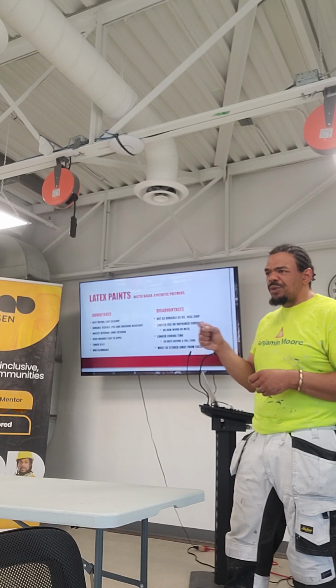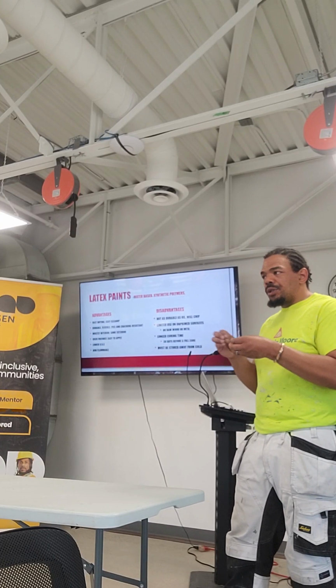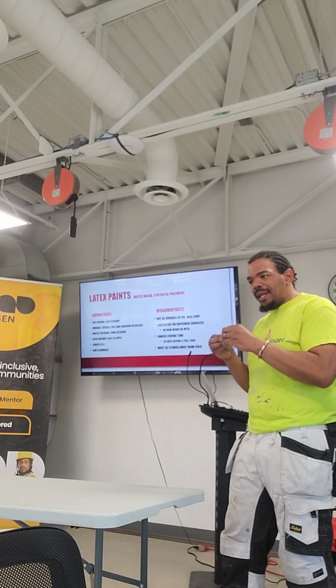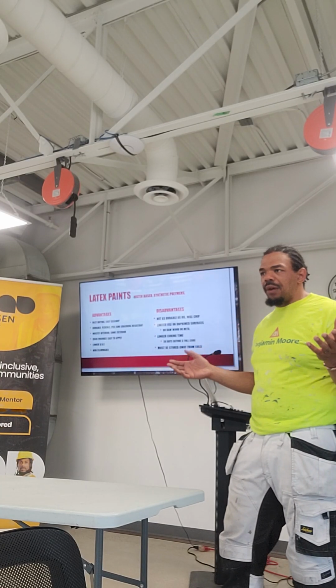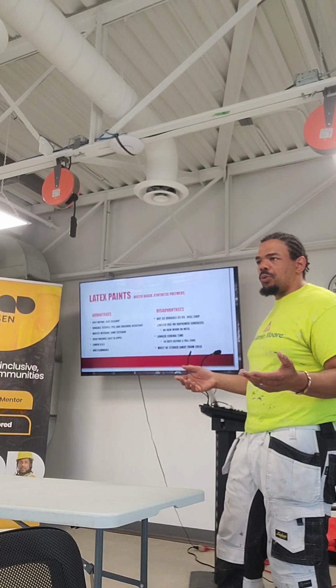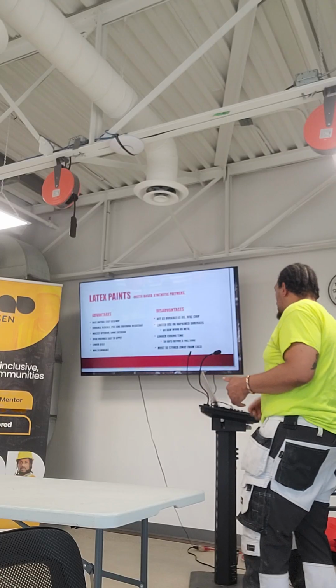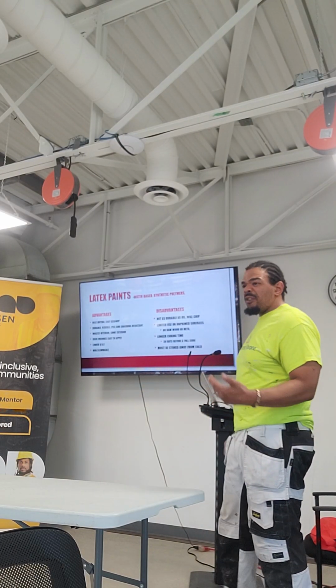Sometimes you'll see little crystals in it, even after it's completely dry. Those are the pigments in the binders that coagulated. They got together and they just locked into each other, and now you can't really use the paint. It's basically just water for a wall. It's a colored water. You really can't use the material after that. So you have to keep latex paints away from the cold weather. So they're very finicky with weather.